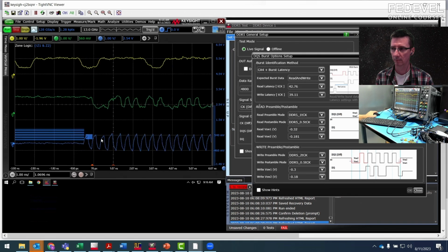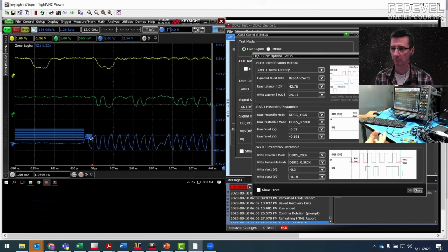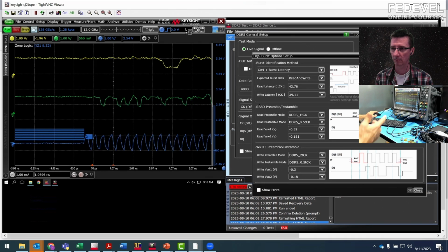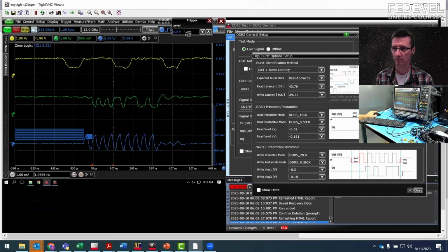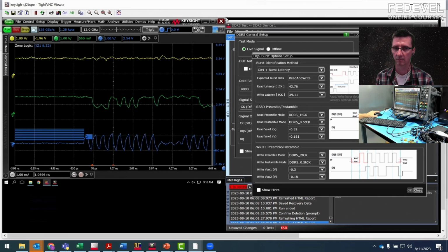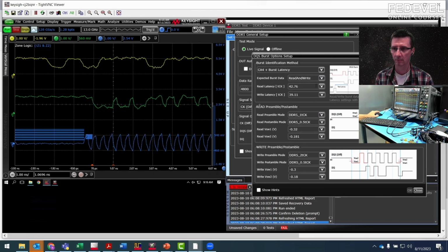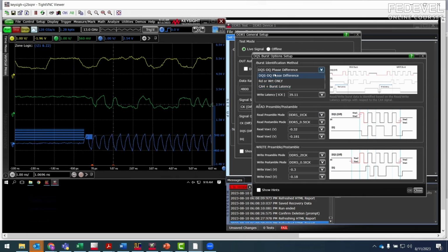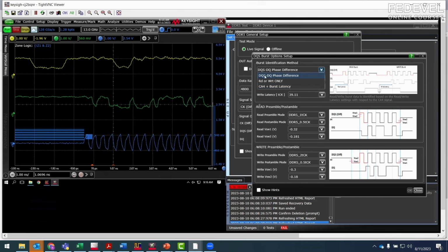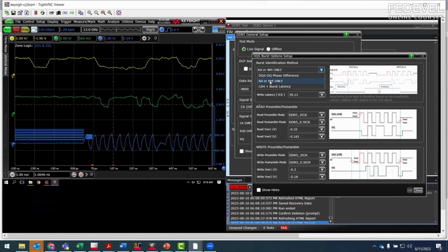This is nice for visualization, but the specs I'm working from include a spec for the read burst and a different set of specs for the write burst. So the software has to be smart enough to determine that. There are different methods we use. We can measure the phase offset of the data and the strobe, or, if we have the ability to only transmit a read or write burst.